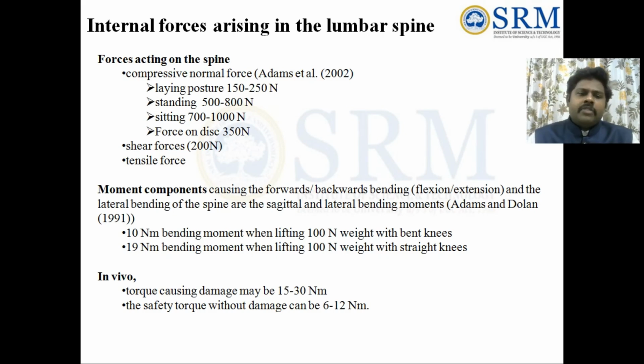Now, if I am taking the moment, for example, flexion and extension are done with respect to the moment. So what is the maximum moment a spine can carry? For the cervical spine, for the testing level we are taking it as 1 Newton meter, and for a lumbar spine we are taking it as 10 Newton meter. The maximum failure for the cervical spine we can take as 2 or 3 Newton meter, and for the lumbar spine as 15 Newton meter.